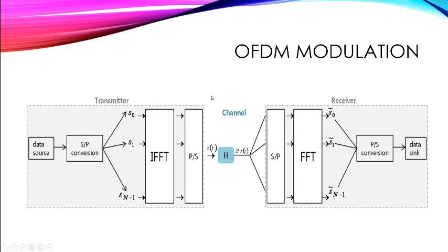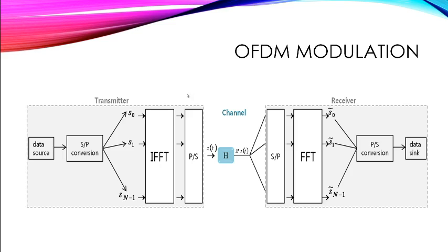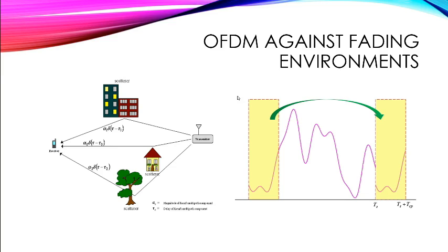So now I will explain why the OFDM modulation is very important for new generation communication systems. The advantage of the OFDM is that it divides a high data stream into parallel low data streams that are transmitted simultaneously over n subcarriers. For the purpose of this standard, each OFDM symbol will have 64 subcarriers. The receiver will be able to demodulate each of the signals and avoid inter-carrier interference because they are orthogonal with each other.